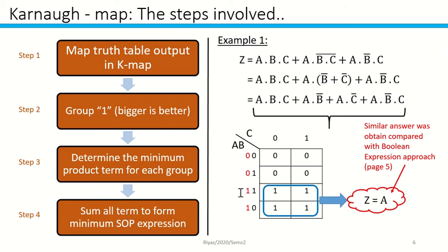Be careful over here, because usually we write 00, 01, 10, 11, but here the 10 should be at the bottom and the 11 over here. Please write in this order, to avoid any problems in the future. For the C input, you only have two possible values, C bar or C, that means 0 or 1.